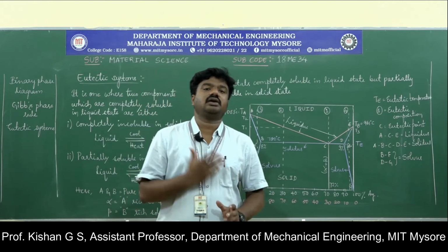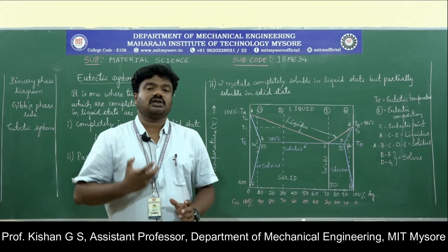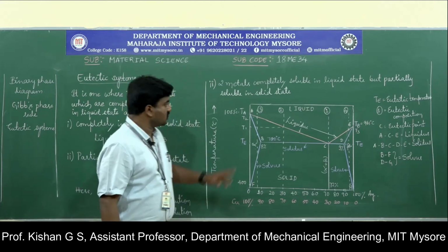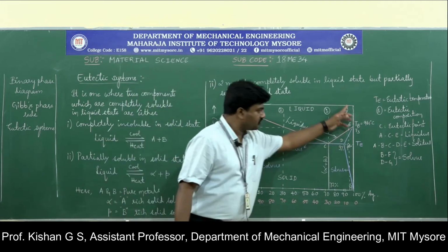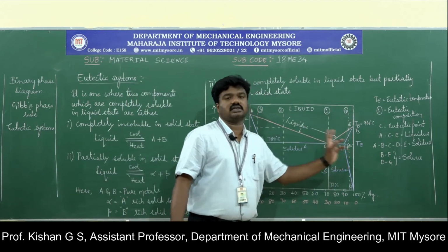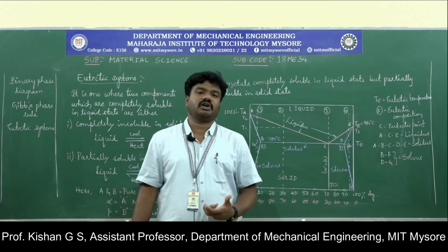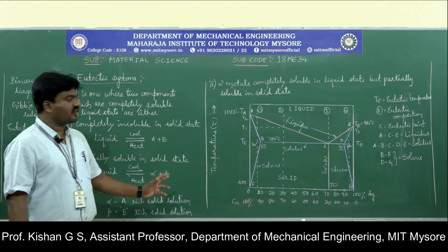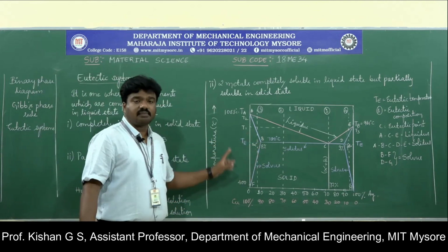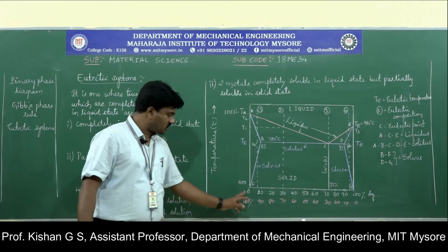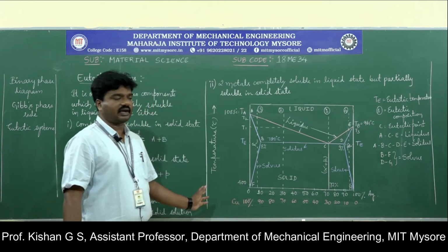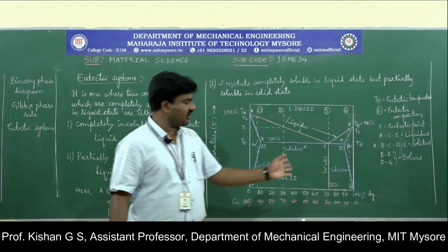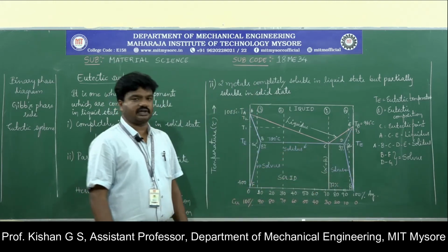Here, we mandatorily have to take two compositions that result in the partial solubility of the two metals. So that is composition 3 and composition 4 here, wherein it lies in the range where partial solubility is considered. So alpha and beta, as we have defined here: alpha is the rich mixture of A material. Here the material A is copper, which is taken towards the left side, and beta is the rich mixture of silver material, since silver is taken towards the right for the representation.